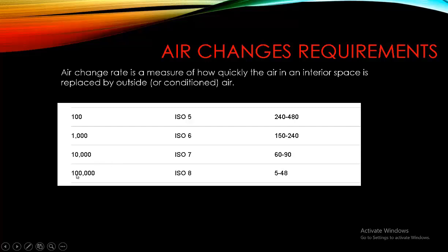And in class 1 lakh, or you can say class 100,000, 5 to 48 air changes are required per hour. So these are air changes, and these air changes also affect load calculation.